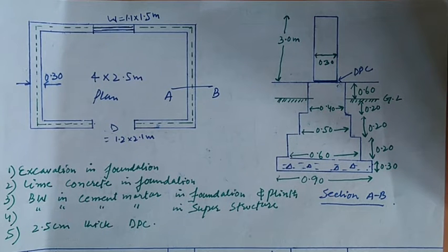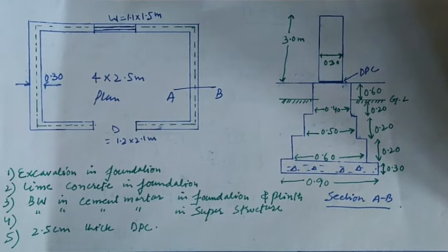In this method, the length will not change, as we have seen in the last method, that is the long wall and short wall method, where the lengths were changing. In this method, the length will remain the same throughout the structure, that is from foundation to the superstructure. But when there are cross walls or junctions, the length will change. For buildings having a cross or partition wall, for every junction of the partition or the cross wall with the main wall, special attention needs to be paid in order to find the correct quantity.